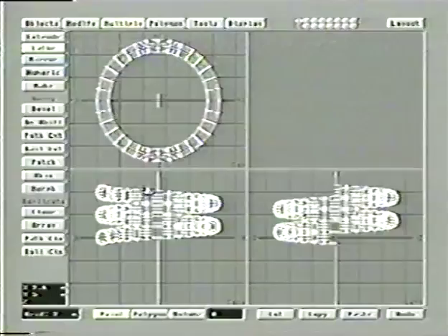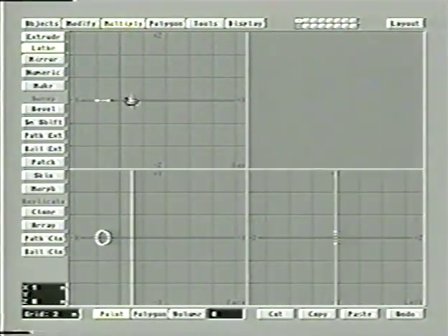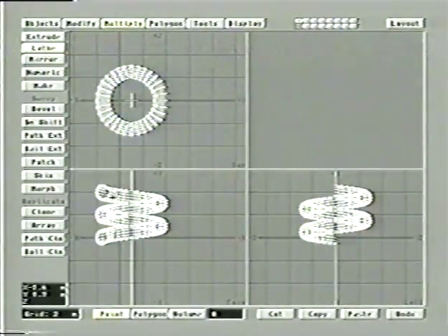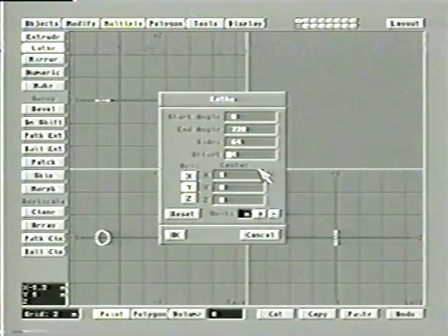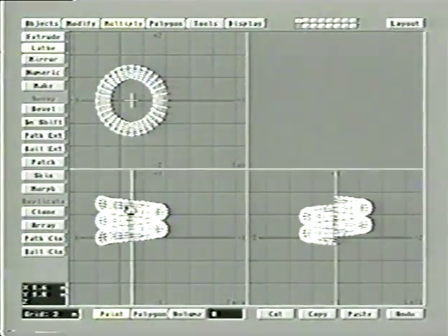So it looks a lot rounder. And if we were in fact to undo it here, let's just undo that and bring the pole in a lot closer. Now you see where we can start to get that sort of spinning cord type of thing. There's a lot of things you can do with this. A coil spring, for instance. If we want the parts touching right on top of each other, it's just a matter of lowering our offset. With the offset of 4 meters, they're not quite touching. Undo, go numeric, change our offset to, let's say, 3. Now they're touching each other right there.